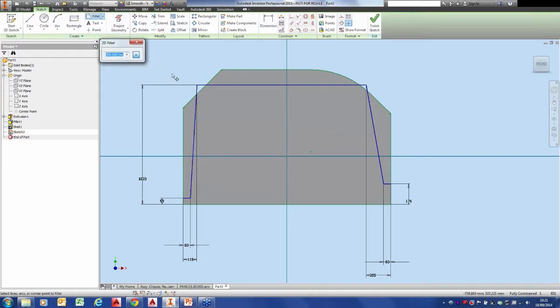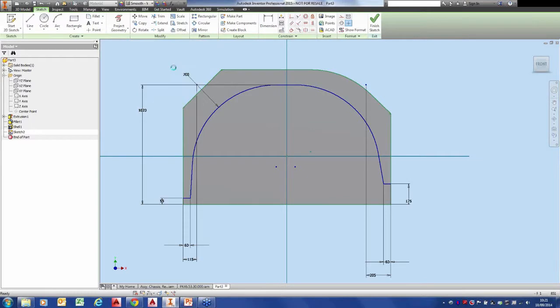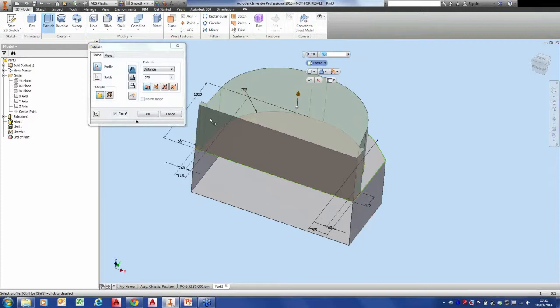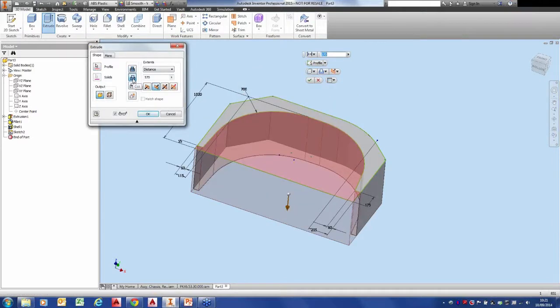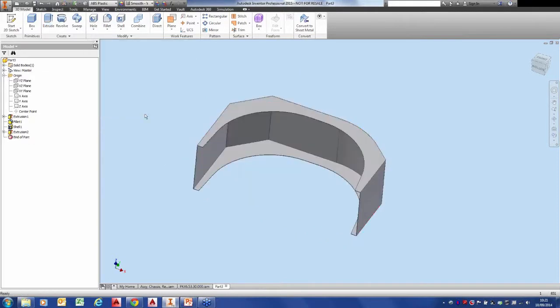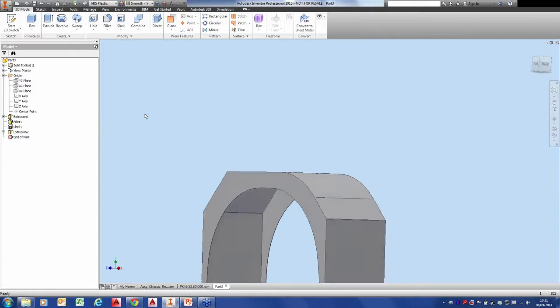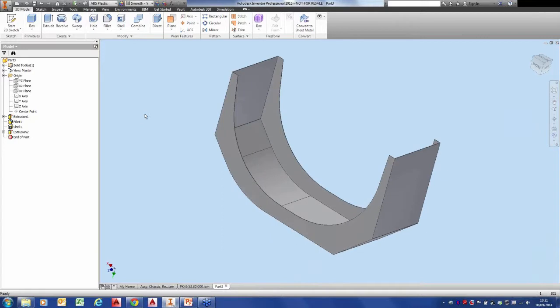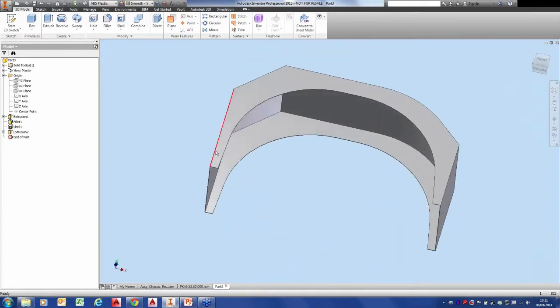So again, 700mm, it recognises it from last time, so again it speeds you up. So I pick the lines I want, and then I can just finish the sketch. So using my extrude tool, I can pick the profile I want. I can then say cut, I can say to next and go OK, and that will remove everything. So I've now created the profile I'm working on. So I've now got one component.